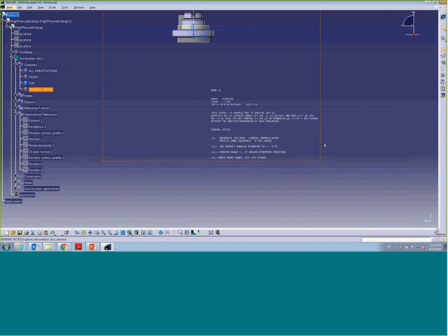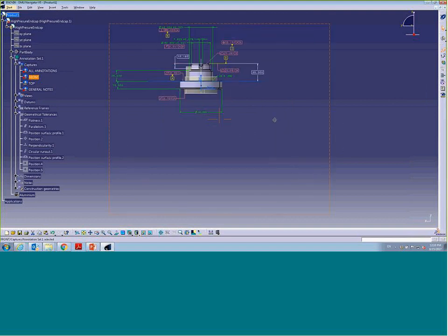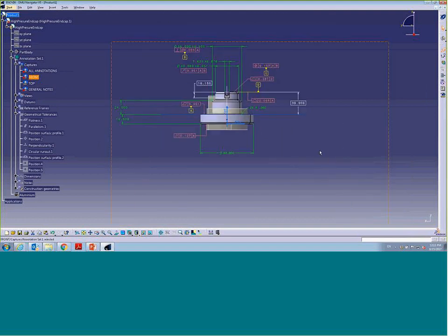Okay, so what else you want to do is perhaps capture those images. Let's say I'm going to capture the front, or display capture, which is the front view. And I want to capture this view and maybe print it for external use. So you can go Tools, and there's an option Capture. It's not actually Snagit or Windows Snippet or anything. It's actually much better too.